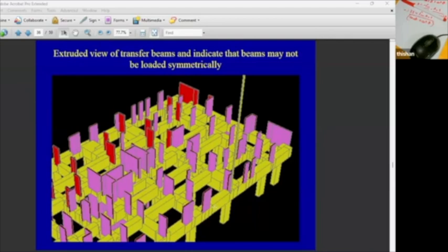But in this particular building, they wanted it flush, so we had no other option, and we actually got 25 millimeter bars at 100 millimeter centers in certain locations. The huge amount of reinforcement, but unfortunately you can't avoid it. Is that clear, Bandhuka?